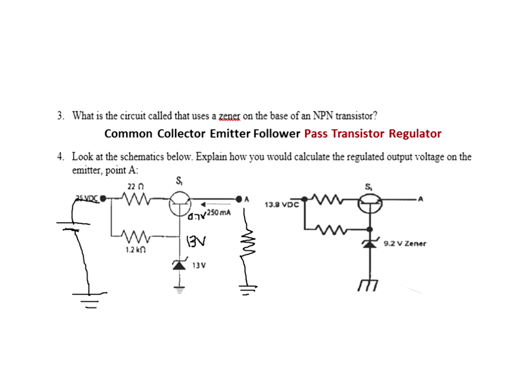Now, how many volts do I lose right here between the base and the emitter? 0.7. So how would I find the voltage up here? 13 on the base minus 0.7. So how many volts would I have on this load right here? Yeah, 12.3. The answer to this problem would be 12.3. So that's how that works.